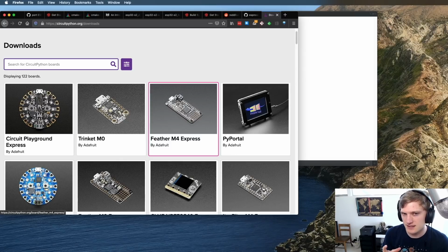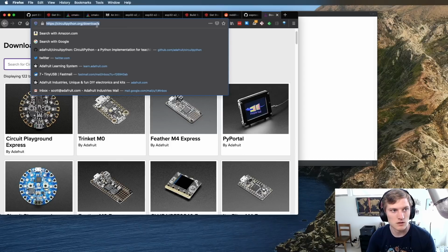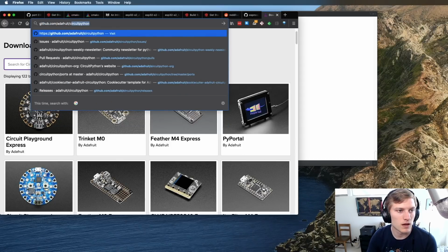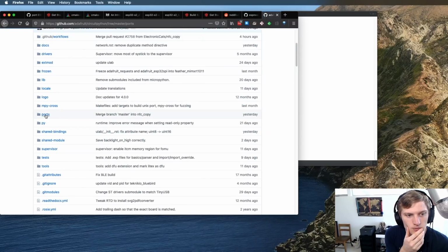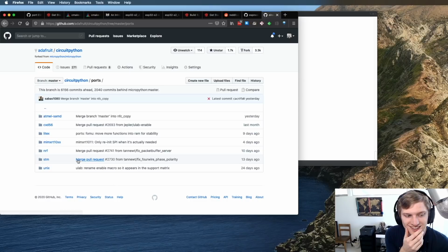But I don't know. It's one of the things I've got to stew on, because my next steps are kind of like, okay, TinyUSB works. It was awesome, right? It just popped up. So I'll create a new directory, ports/esp32s2. If we pull this up, we can see that we have a ports directory. This is growing, which is awesome. We recently added LiteX, which is Python-based FPGA stuff, which is really cool. So we'll add an ESP32-S2 here.